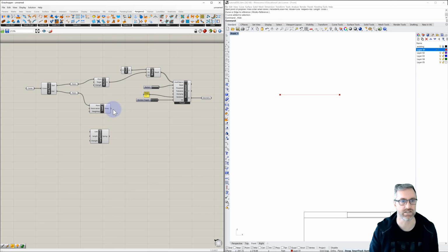So let's take a look at it. Let's look at how we load that point. We're going to take a force vector. So we could say Z in this case because Z is vertical. And I'll plug that in for the force vector. And for the force, I'm going to intentionally do this incorrectly, but we're going to create a panel. So // and let's say 1. This is positive, meaning that the force will be going up instead of down, which we would expect. But now let's plug the load into the merge.